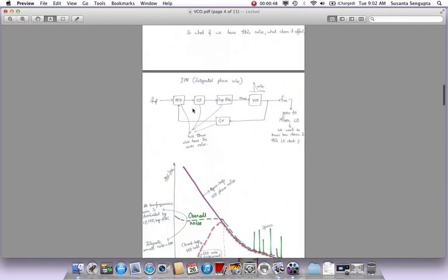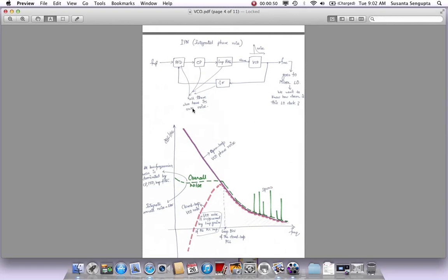lower this way. Okay. So the first thing we will talk about is what we call IPN, integrated phase noise. We mentioned this briefly when we were going through the RX section. Where you have the clocks, this VCO is generating some clock, and this is the whole PLL again, and the VCO is generating the clock, and the clock after some division or no division, whatever it is, those square waves are going to go to the mixer as an LO, right?